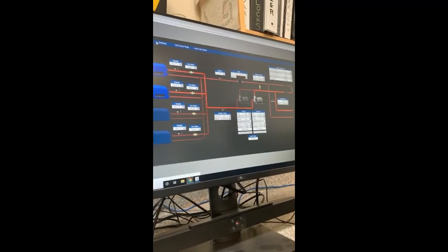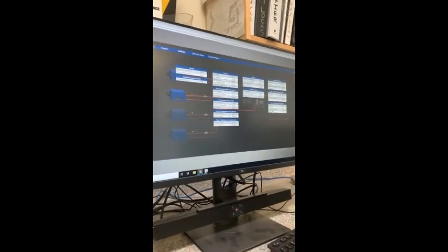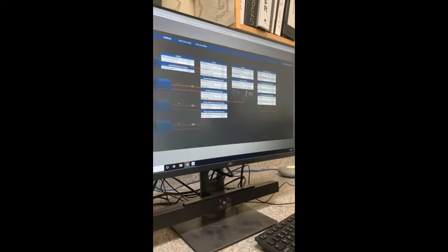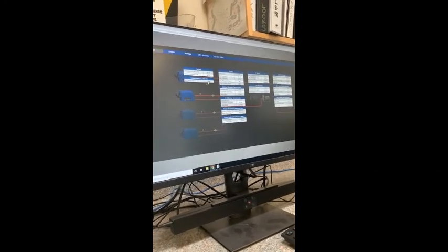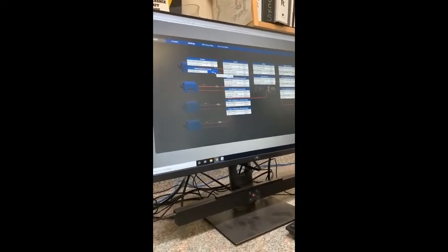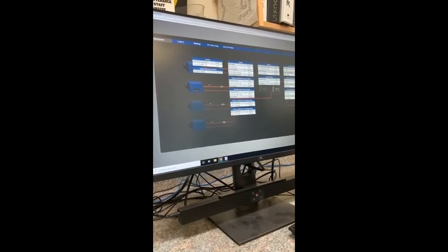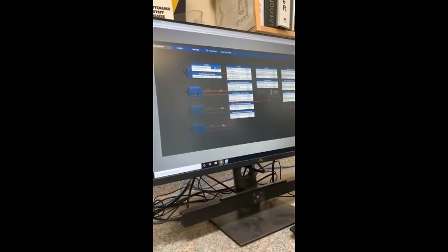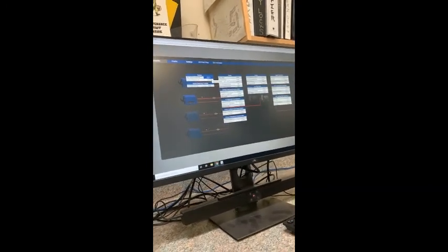Again, we have a settings portion of the page. A lot of it is alarm set points, some pump start and stop delays, minimum and maximum speeds, the rotation intervals, a balance override for all the hot water valves in the building, and an outside air temp lockout where it won't allow the heating side of this to work above 120.